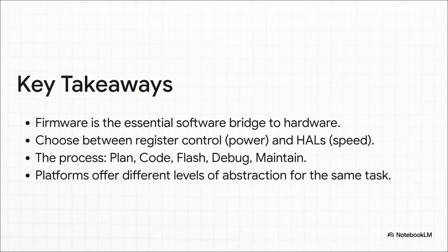So, to wrap this all up, what are the big things you need to remember? First, firmware is that vital software bridge that makes hardware actually work. Second, you've always got this choice to make between the raw power and control of registers and the speed and simplicity of a HAL. Third, the process isn't chaos, it follows that clear path: plan, code, flash, debug, and maintain. And finally, the way you write code really depends on the platform's level of abstraction.